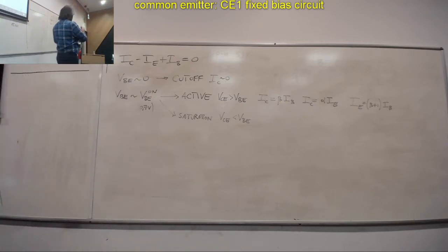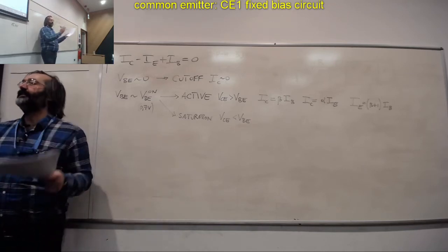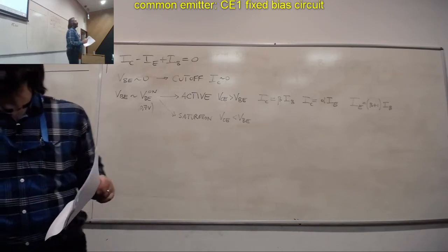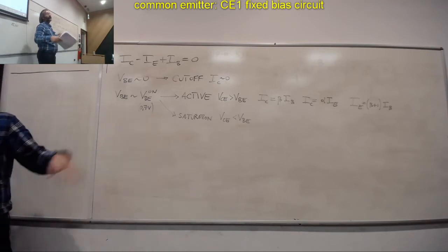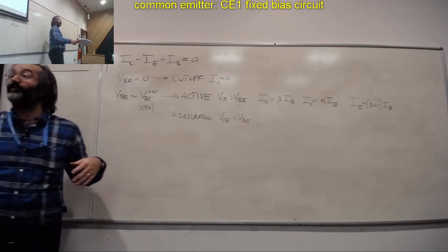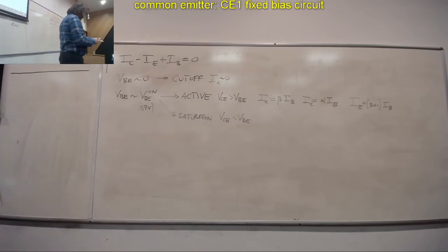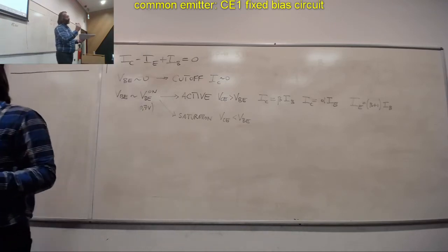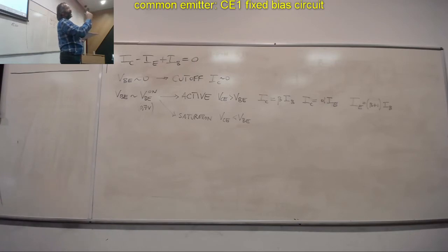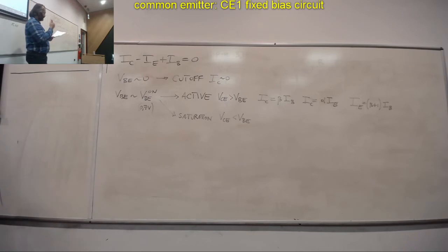What happens when I make a design and in my mind, it's according to the data sheet, I'm fine, but these numbers may vary from transistor to transistor. What happens if the temperature changes? So we need to consider the stability of the design as well. How well, in the end, the circuit we will build will actually operate at that specific IC and that specific VCE that we were planning to.